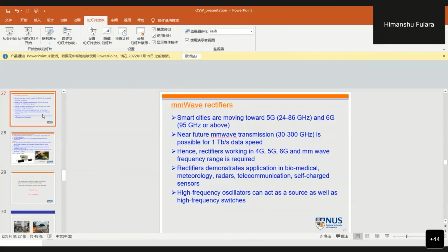Professor Vincent, I have one question. Yes, sorry, maybe I missed it. In the first part, you said that you have to achieve an optimized impedance mismatch when you put several of these oscillators together for the rectification, and you have to combine parallel and series connections, right? Right. I wonder what the best performance is, in terms of the number of parallel connections compared to series connections, for example. Do you find any optimum? So till now, the hybrid connections are not working in the way we want. Right now we are doing this impedance matching with only series connections, up to about 10 devices or a single device. With hybrid, there are problems like increased capacitance and inductance, which is problematic right now. So we don't have any good results for this hybrid approach.